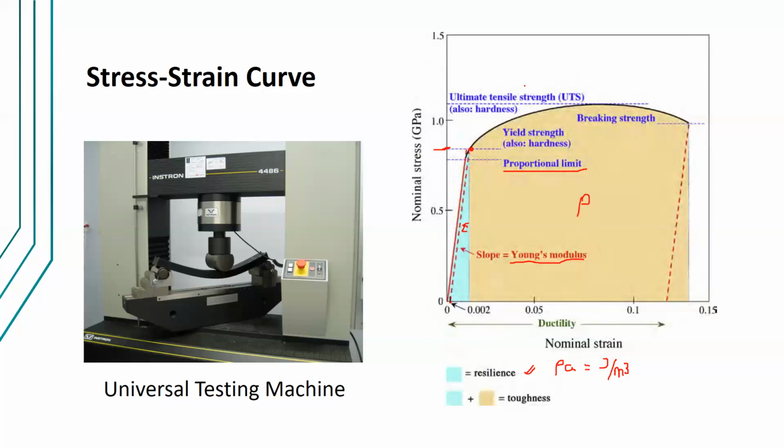Now, before I discuss the other properties here, let me first talk about ductility. So what is ductility? Ductility is the ability of a material to withstand tensile force. So you have a material, you apply tensile force to the material, you pull it, for example, elongate it through a certain force, and that material will elongate. Now, if that material was able to withstand that force, you elongate it and elongate it without breaking the material, so you're able to stretch the material into thin wire, that means the material is ductile.